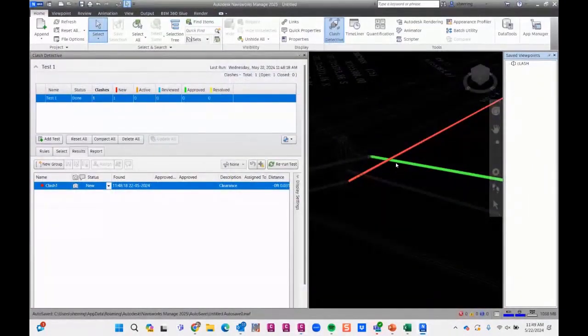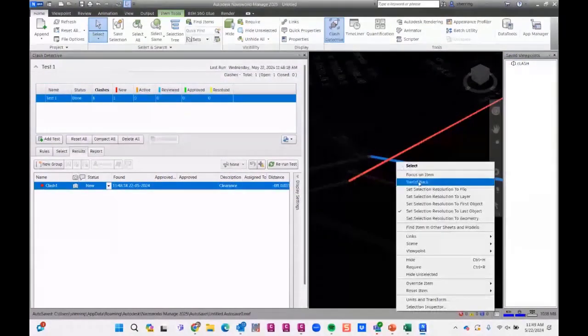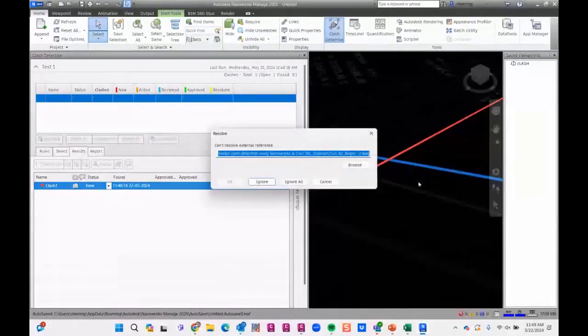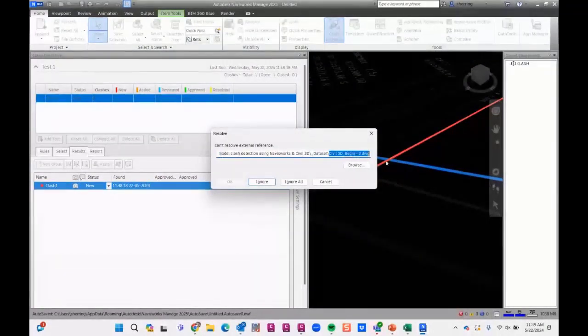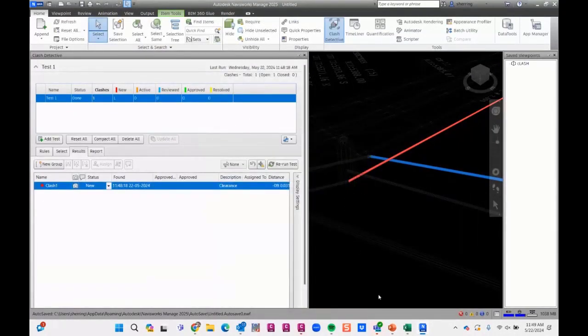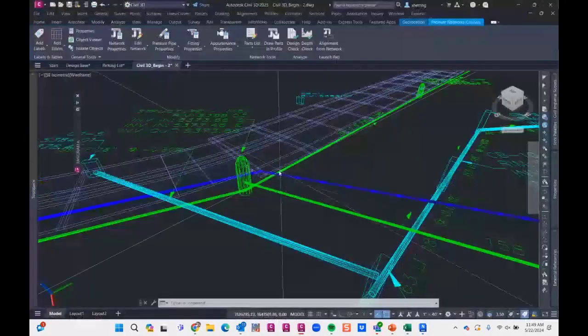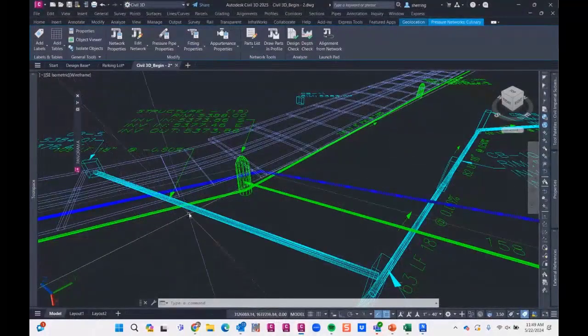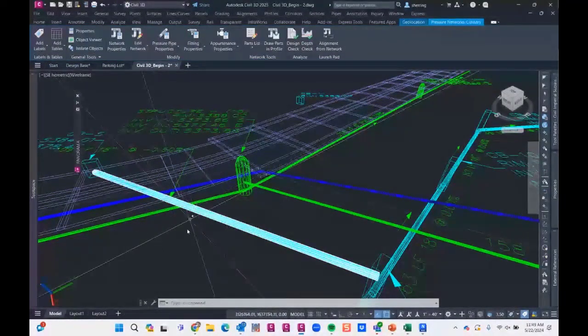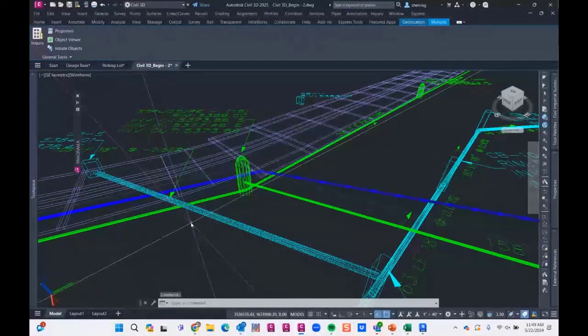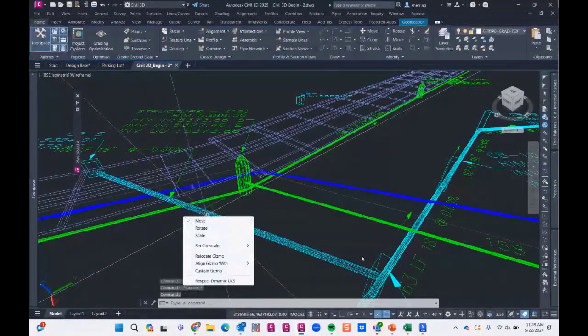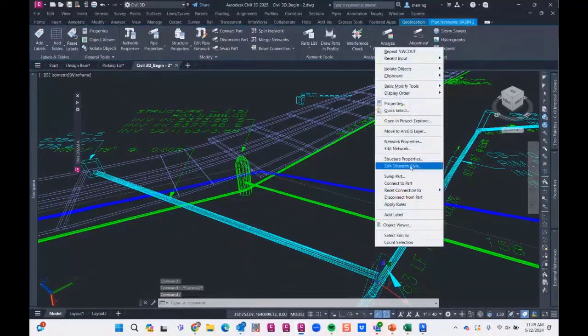In Navisworks, if I select, let's select this pipe. There's a switchback. If I go switchback, and I gotta browse that file, I know. If I go back to civil, it zoomed in and selected that pipe in a 3D viewer. So I knew that clashed. I could just grab my clash pipe. And if I needed to change something in my pipe or my structure, I can make that change. So it saves a bunch of time if you have a whole bunch of clashes in there.